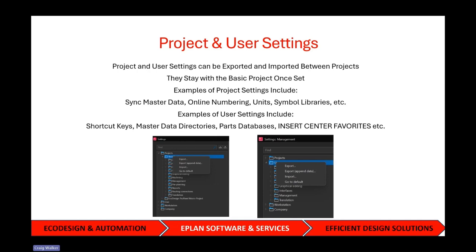When people change between machines or even try and provide help to someone else in the company, they're able to guide them directly to this through the same interface and the same setup and layout that they're used to on their own machine. So it's good to have that set up as a company initiative. Insert center favorites is another one there. If you use the insert center quite heavily, your favorites are saved under user settings and exported, and that way someone else can go to the favorites on the insert center and pop things in pretty quickly, and it's saved the same favorite setting, favorite group.